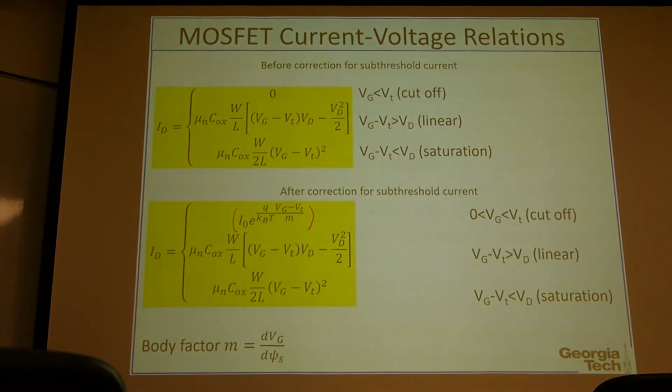Actually, let's remove it. So this is the threshold, sub-threshold current. Basically, when the gate voltage is smaller than the threshold, then the drain current exponentially depends on the gate voltage. So that's the only difference we make here for this cutoff. Now we call it sub-threshold.